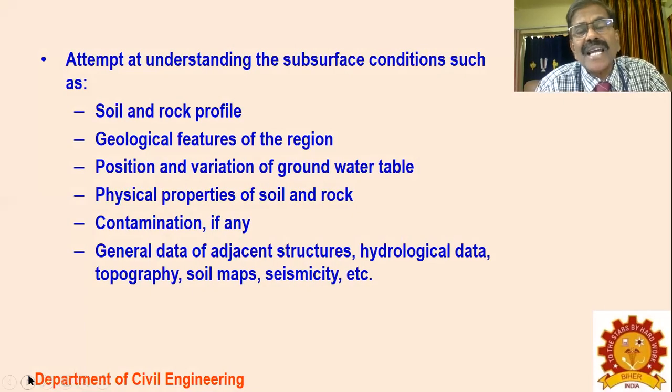So, in an attempt at understanding the subsurface conditions such as the soil and rock profile, geological features of the region, position and variation of the groundwater table, physical properties of the soil and rock, contamination if any, the general data of adjacent structures, hydrological data, topography, soil maps, and seismicity, etc. So these are all the subsurface conditions which you need to understand when you go for the soil explorations or